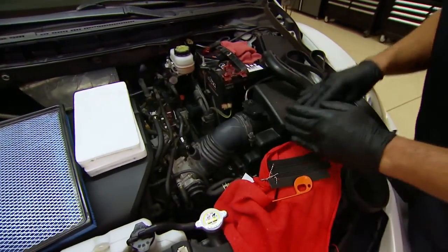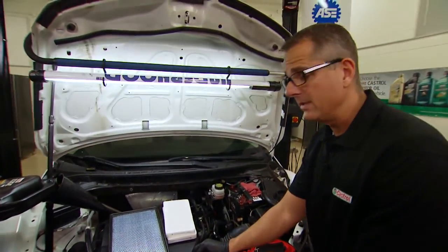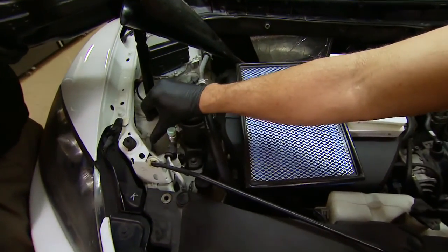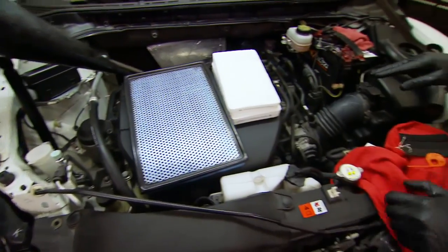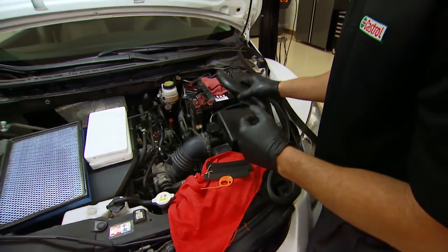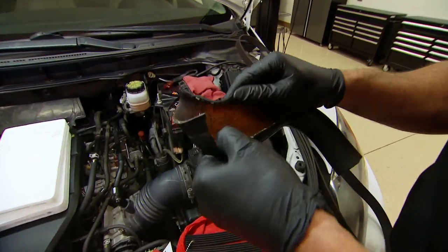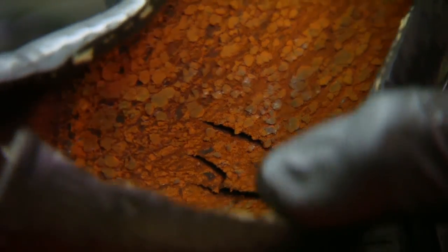Make sure that you look at all the systems that are available to you. Come over here to your coolant, check your coolant, and then over here is the power steering fluid. Over here you also have some wiper fluid that you can use. And when you're checking the belts and hoses, I have a couple examples for you. Your hose may look good, but you want to feel it. Make sure it's pliable. And if you look inside this one, this hose here is not in that good a shape. So you want to go ahead and recommend that to the customer.